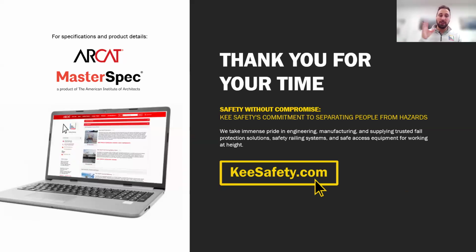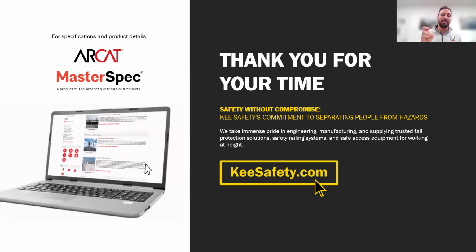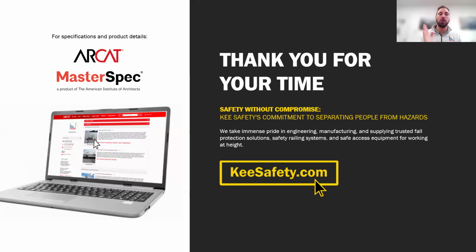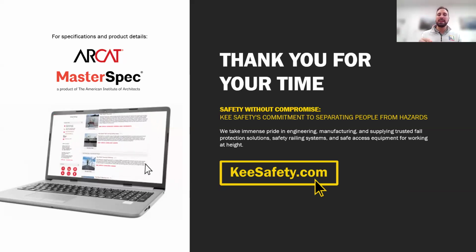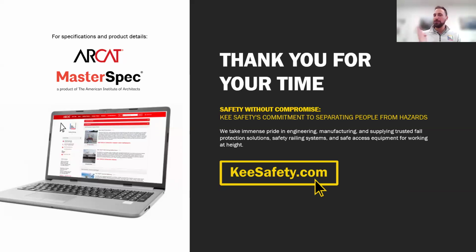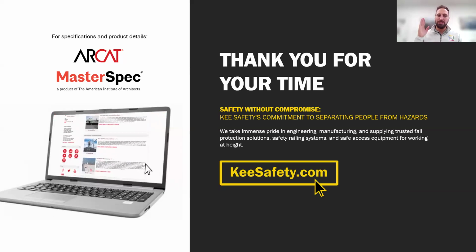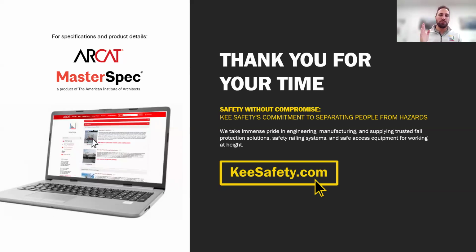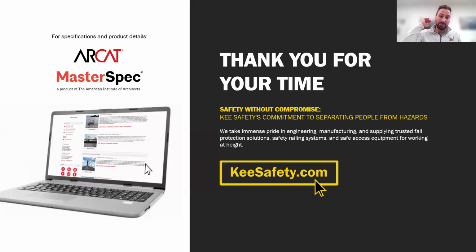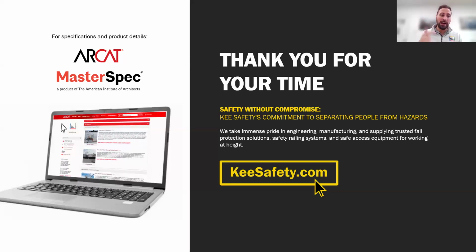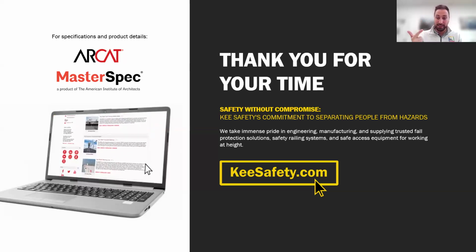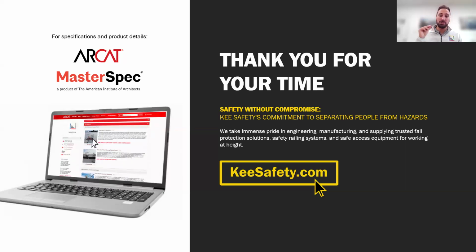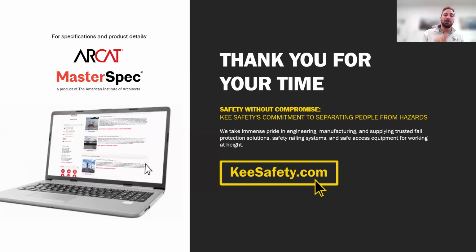And so in the code, what OSHA is saying is that the safe working distance away from the edge is 15 feet or more for temporary and infrequent work. So if I'm 15 feet or more away from the roof edge and my work is temporary and infrequent, that's what they consider safe working distance. I'm there all the time, so it's not infrequent work and it's not temporary work, then that exemption doesn't apply.